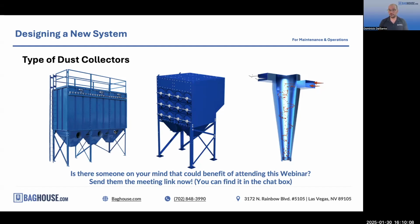Now, cartridge collectors, though, offer a very good alternative sometimes because they're smaller, more compact. So they're cheaper to make, cheaper to run. They're a little bit easier to work on, changing filters. They're really good for applications where you have a light dust, or maybe you have a lot of air you have to move, but a little bit of dust. Think like a welding application. You gotta move a ton of air from the whole building, but only a little bit of dust. If you had a bag house do that, it would be huge compared to a cartridge collector.